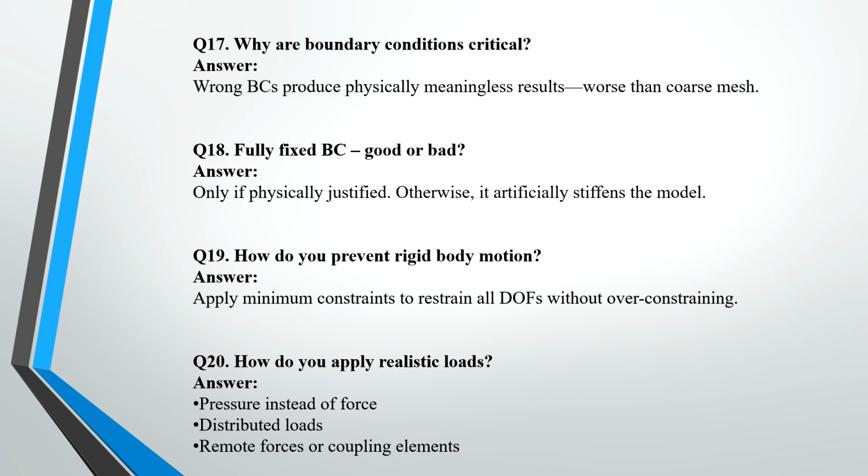How do you prevent rigid body motion? Apply the minimum constraints to restrain all degrees of freedom without over constraining. How do you apply realistic loads? The answer is pressure instead of force, distributed loads, remote forces or coupling elements.